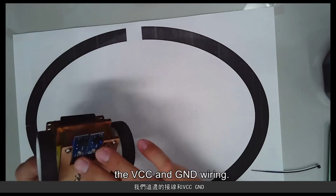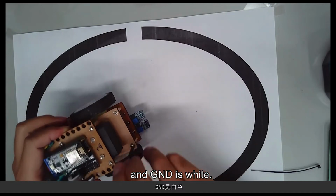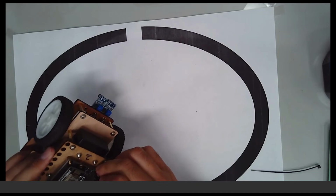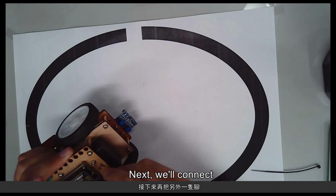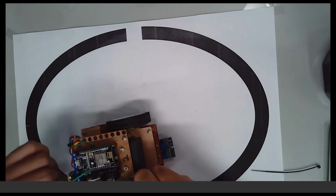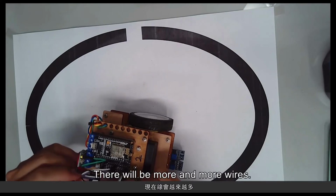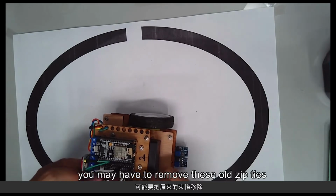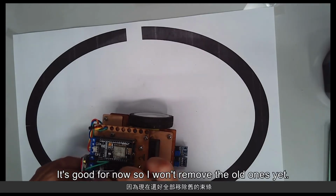Okay, let's take a look at the VCC and GND wiring. VCC is gray and GND is white. We'll connect them. Next, we'll connect the other pin at the 0. We'll grab a zip tie and fix this in place. There will be more and more wires. After a while, you may have to remove these old zip ties and tie new ones. It's good for now, so I won't remove the old ones yet.